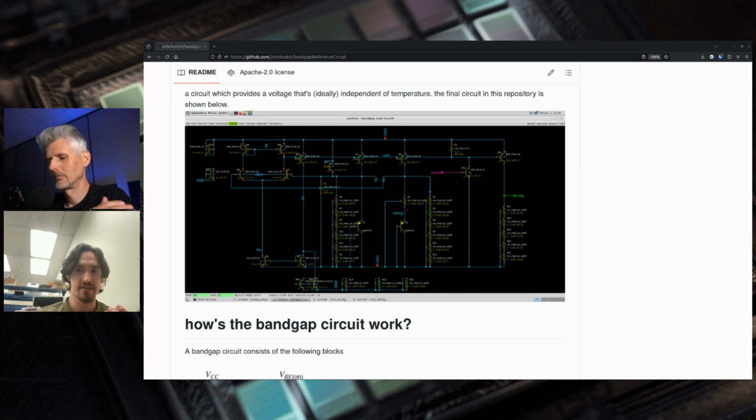And what the dummy does is it allows the processing steps to perhaps screw up a little bit on that edge because it's transitioning from different areas of the silicon. But because it's a dummy, it doesn't impact your circuit. And that was a very high level as a student, so maybe not the most technically accurate, but that's how it works in my head.